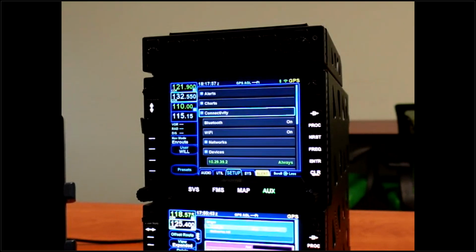So the Sentry devices, you're correct with saying that they are Capstone, extended GDL90. So right here, what you're going to be able to do with your Sentry of any model and your iPad is transfer flight plans back and forth to and from the iPad/IFD, but the ADS-B data is only going to remain on the iPad, and that data is only going to work with ForeFlight.